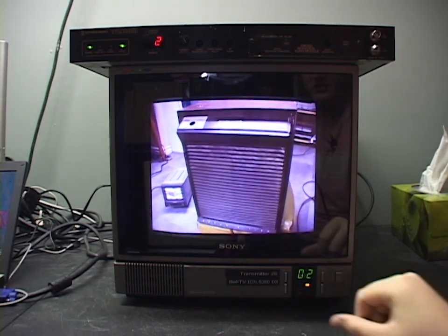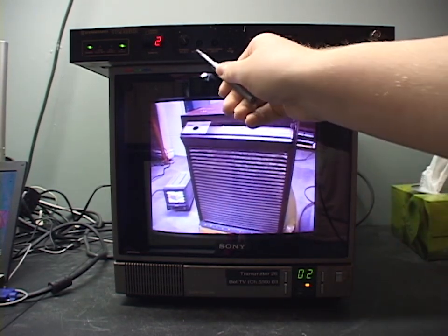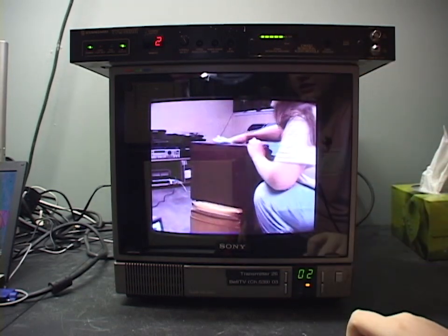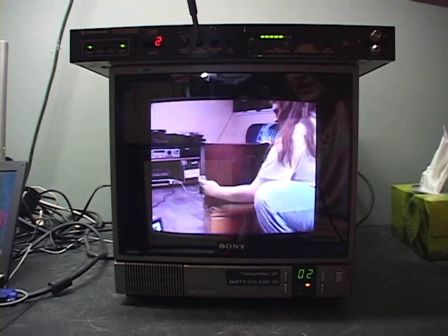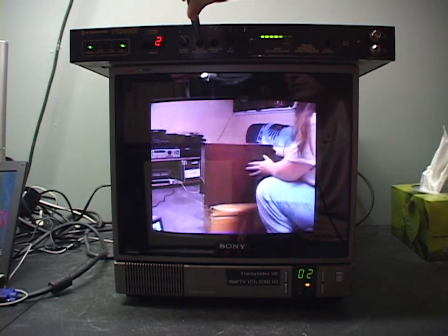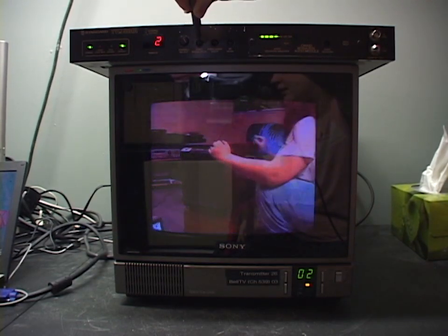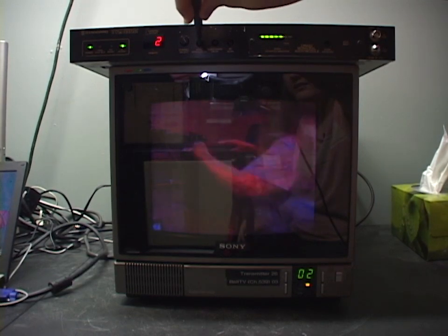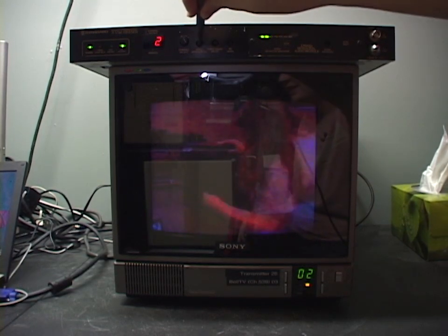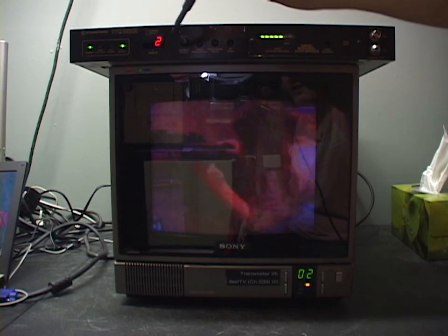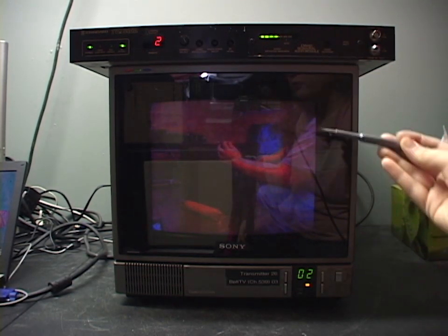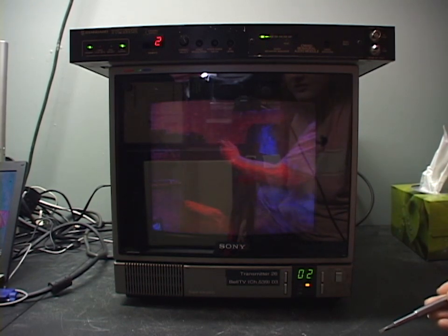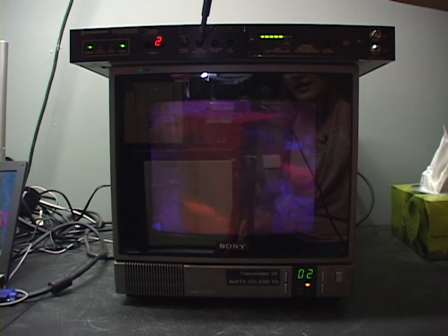So next I'll show you what adjusting the video modulation knob does. What you'll find is that if I turn it down, you can see the video gets darker. And actually it's kind of an interesting thing where the luminance signal seems to have lowered the most, but the chrominance signal hasn't lowered as much.